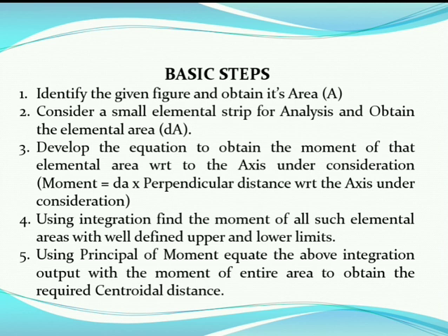Now next, in the third step, develop the equation to obtain the moment of that elemental area with respect to the axis under consideration. That is, what is moment? Moment equals dA, which is the small elemental area, into the perpendicular distance of that small elemental area with respect to the axis under consideration.